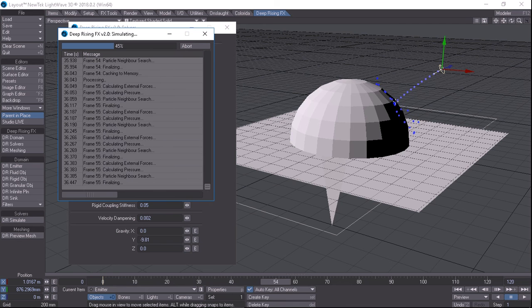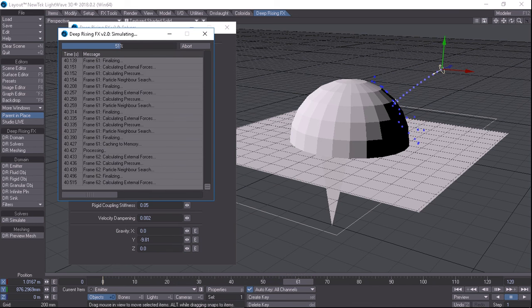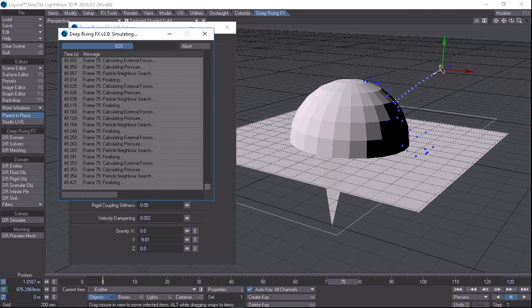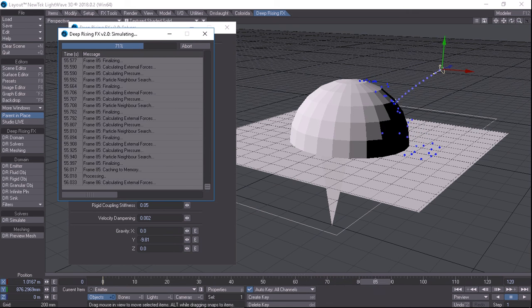So everything we talked about in the first video is happening here. Each particle has a velocity and mass, and every time it collides with another particle, whether it's a boundary particle or fluid particle, it's going to do the calculation of pressure, do its Navier-Stokes equation. It's going to solve that and make sure everything is physically correct, so you get things that look like fluids.